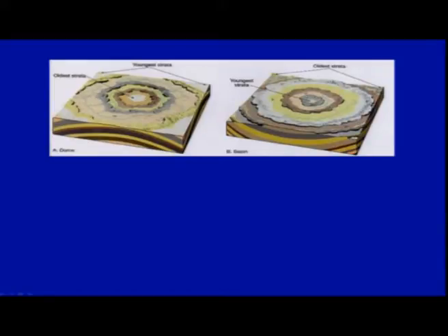Whereas if you have a basin or syncline, the drainage moves towards the center. And the dip has been shown here with the smaller symbols. This is the strike and this is the dip direction, this is the strike and this is the dip direction. So they are dipping towards each other. So you have the syncline here, whereas here similarly you have the anticline, which dips outside.